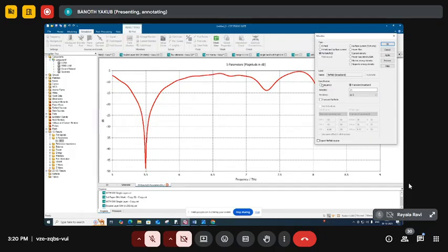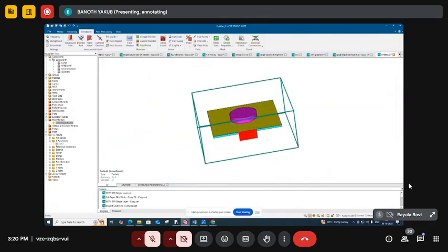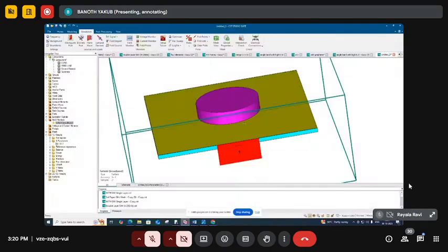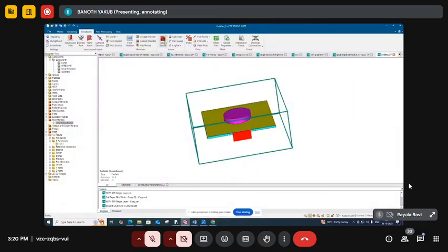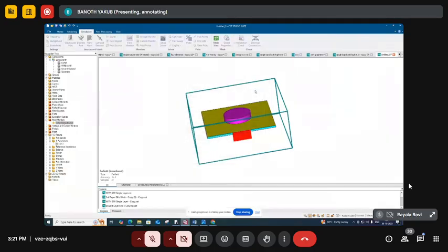After the specification, you change the selection from frequency to transient broadband. Just apply and OK. Then the far field is applied here. Then go to the simulation, and just apply and start. After the far field broadband is applied, you can run it again.